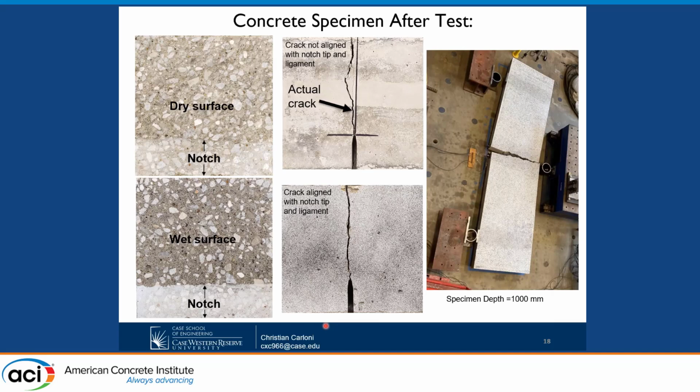And also another thing that we checked is that when the fracture of the surface was all possible, open, the concrete was still wet. And we disregarded those specimens that were dry. If you test concrete and your concrete is in full moisture condition, it will have a strength lower than a dry specimen because of the water in the pores.